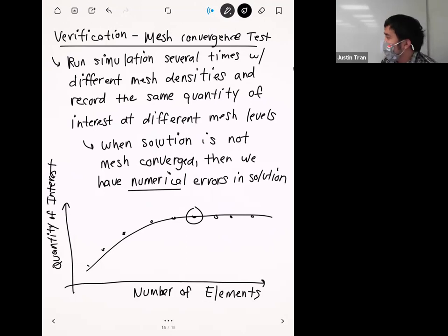And so with that said, I know because I'm requiring it for the final project, and for those of you that did this for the midterm project, you've probably seen already that sometimes it's really hard to get mesh convergence. A big reason why you're probably going to struggle is the limitations of the software. The unfortunate thing with the student or academic version of ANSYS is that they put a hard limit on how many elements you can have in a simulation.